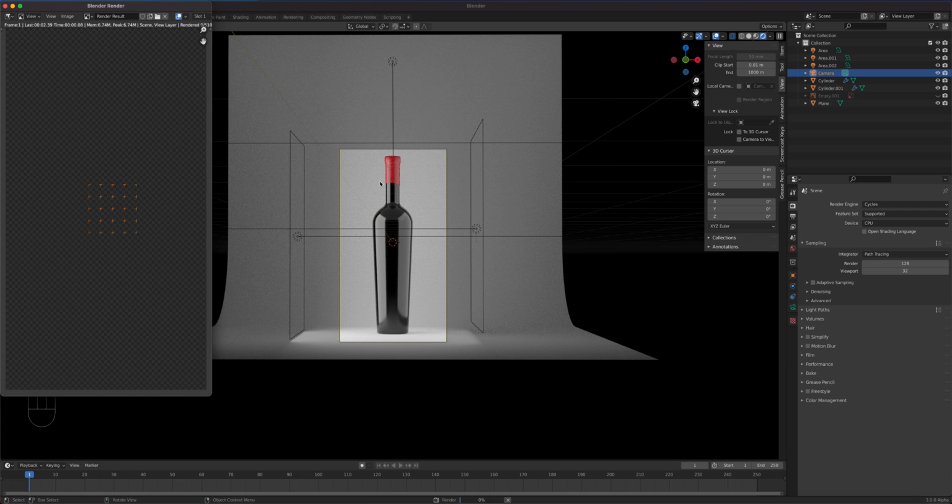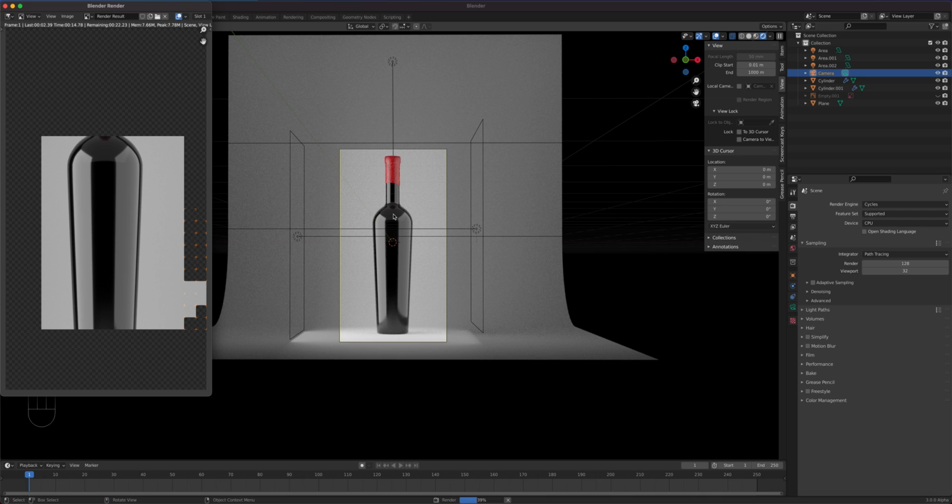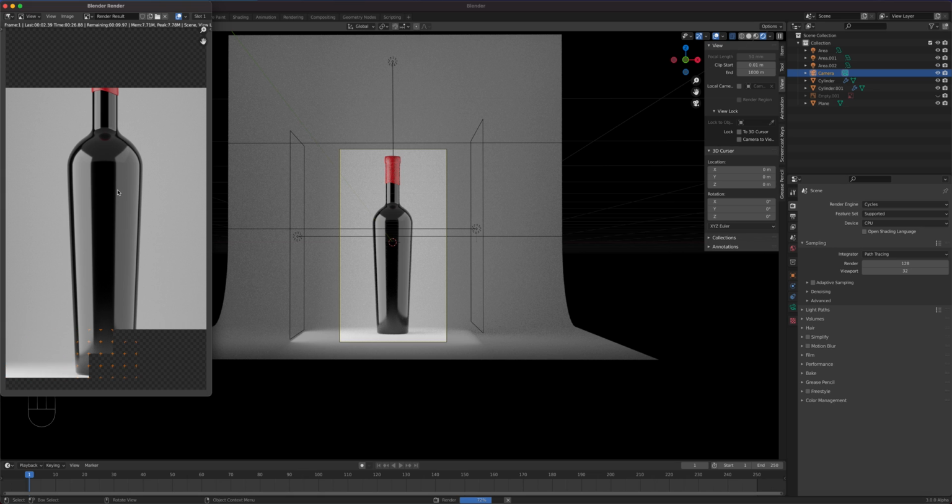As you can see, it's doing its bucket rendering right here, versus Eevee, which should be close enough because it's such simple lighting, and we didn't factor in making it transparent. So Eevee will still lose out to Cycles when it comes to a realistic glass look. But for a glass shiny surface look like what we're using here, it should be fairly close.